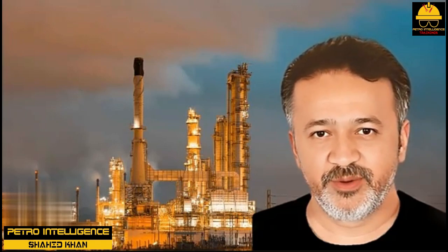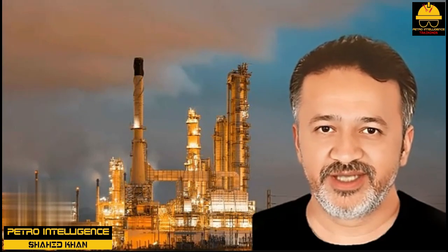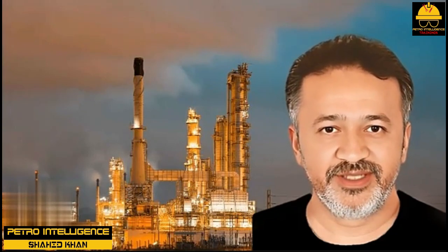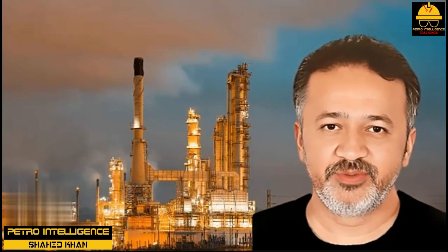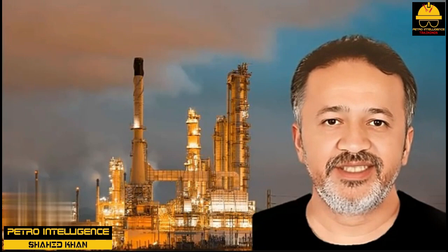The engineer's initial plant inspection showed that the tower top pressure was 24 psig. The relief valve was set at 50 psig. By raising the tower operating pressure to 30 psig, the flooding was stopped, and his contract was cancelled. Why? Ambient pressure at that refinery was about 13 psia, or pounds per square inch absolute, versus 14.7 psia at sea level. Higher pressures reduce the volumetric flow of vapor.